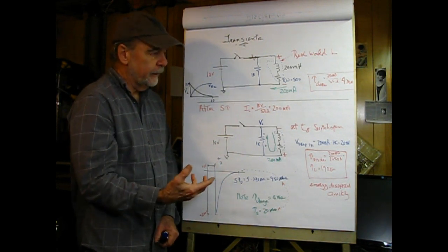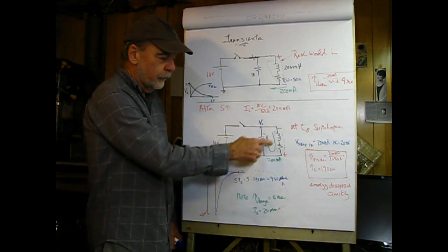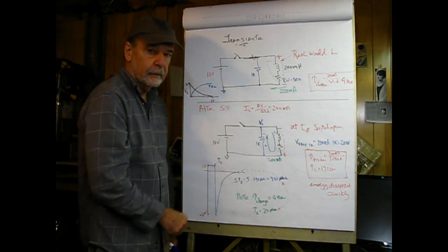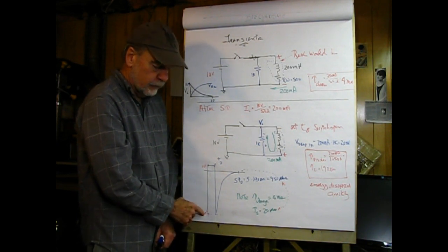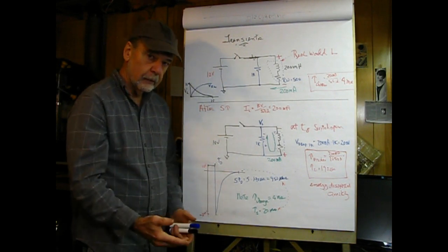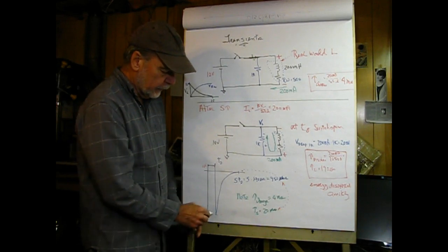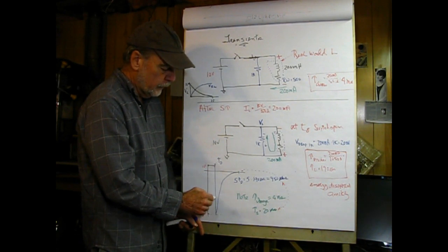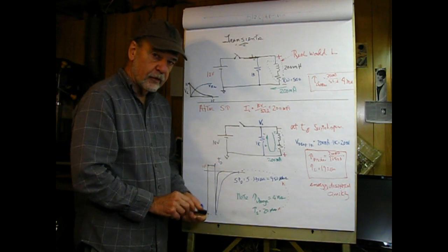So basically, to make sense out of this, if the time constant is smaller, the energy has to be dissipated quicker. And that's why you get this. Now, what would happen if we made that 10K? Essentially, this would go down to negative 2,000 volts. I might say this is crazy, and it might seem like that. The time constant would be even narrower still. It would have a characteristic maybe coming up from the floor, looking something like this. So again, that energy would have to be discharged faster.